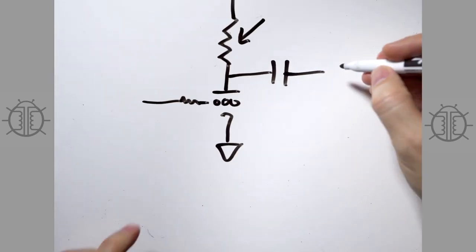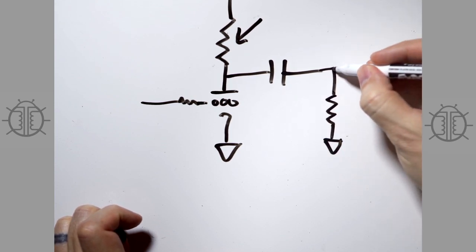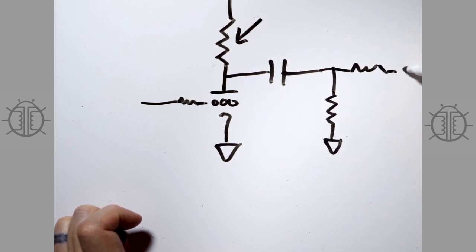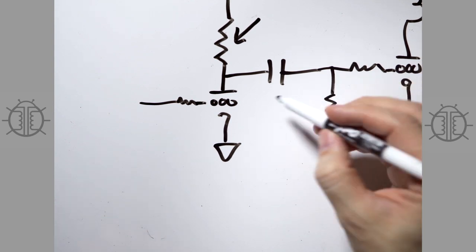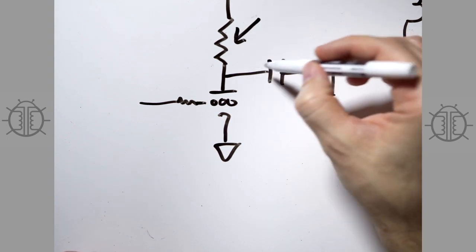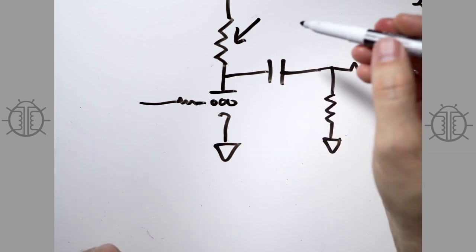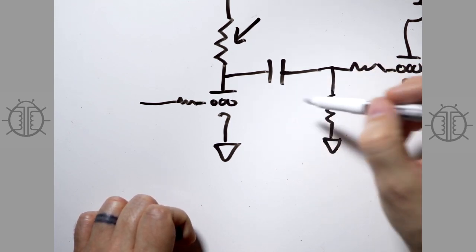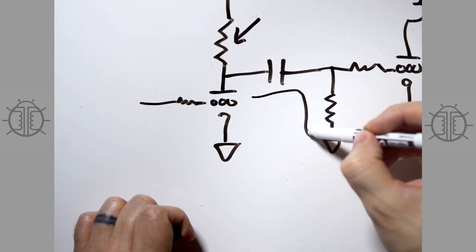But the load up here, which is usually set by the grid leak resistor of the next stage, would look like this. That's the grid stopper. So here's, let's say, our next stage right here, okay? And this is probably an output stage, so let's put a transformer on it, like this. Your speaker will go over there. And so the AC operating point, of course, has to go through this cap, because a cap is an AC short at audio frequencies, or it should be, if your design is right. And so when the AC signal swings, it doesn't just swing here, it also swings this way.